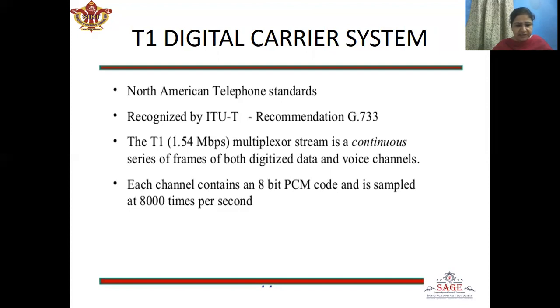Now, each of the TDM signals is analog to digital converted and companded. The resulting digital waveform is transmitted over a coaxial cable. The signal is regenerated by amplifiers called repeaters placed at appropriate intervals.